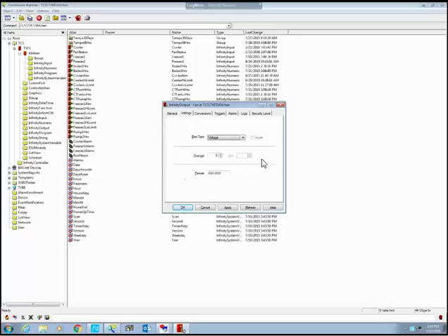We go to settings. This is where we are going to determine what type of output it is. Since this can only be a digital output on this type of controller, I'm going to have to change it to digital. It always defaults to voltage. I'm going to put it on the first output, so I'm going to change that to channel 1. The format is on or off, so I'm going to change it to $sign and 3 pound signs. That's going to show up as on or off.